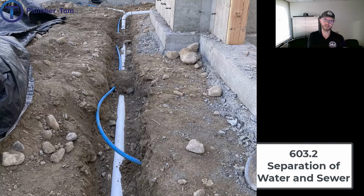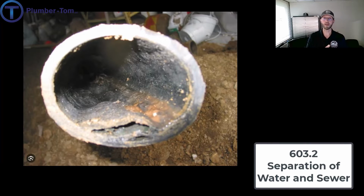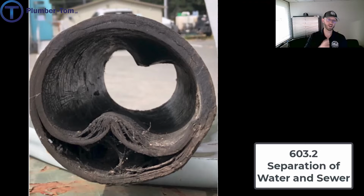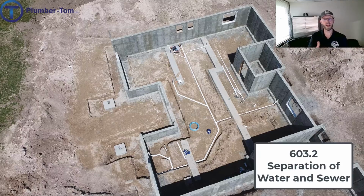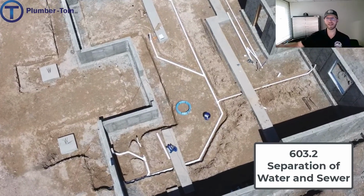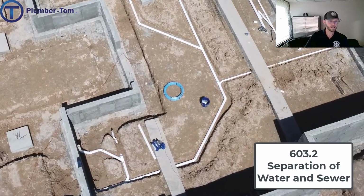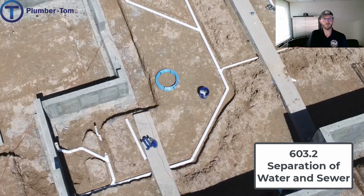But if we are not, and what I'm talking about is the stuff that we used to use. Back decades ago, there was a pipe called Orangeburg. It's kind of like a thick tar paper. It's not really rigid. Many of them are being replaced today because they smash to an oval and they get roots in them. And this is not the kind of pipe that you'd want to have your service in the same trench with. So again, we just check the list, and anything nowadays, like PVC, cast iron, whatever else you'd use for your building drain or building sewer, most of the stuff we can get is on that list, and we can put our pipes together in the same trench.